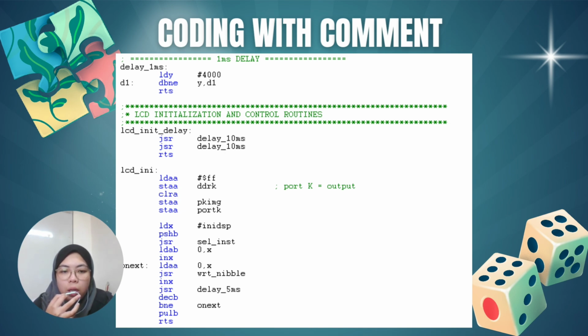This part of code handles timing and LCD initialization. A 1 millisecond delay is created for accurate timing, and proper delays are applied before sending commands to the LCD. The LCD is configured in 4-bit mode to reduce pin usage while maintaining reliable display operation.